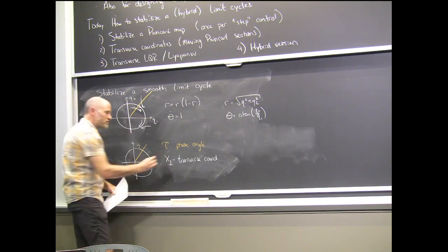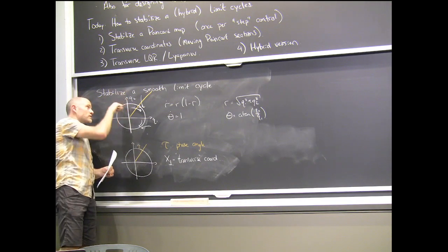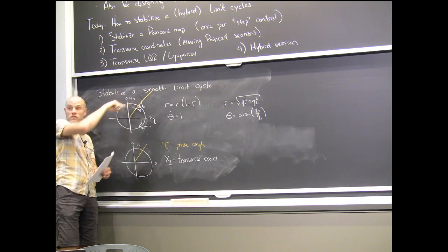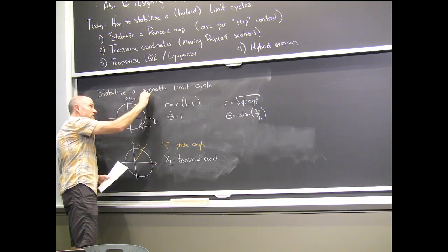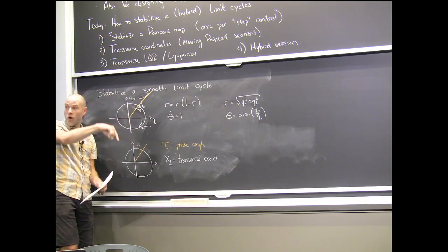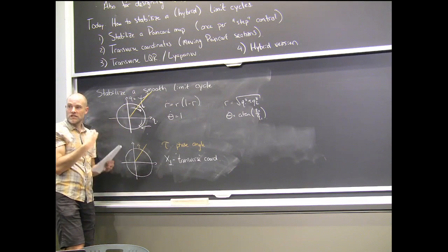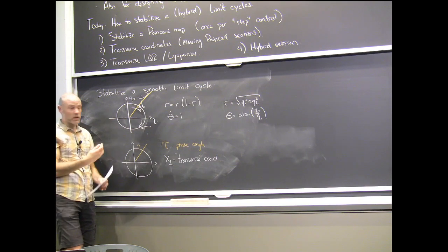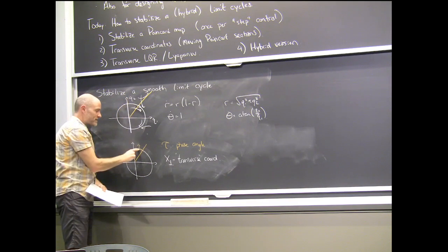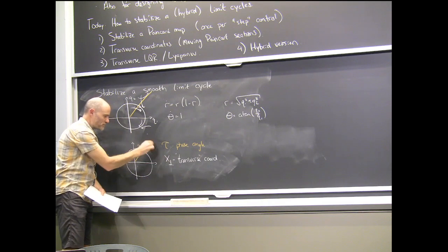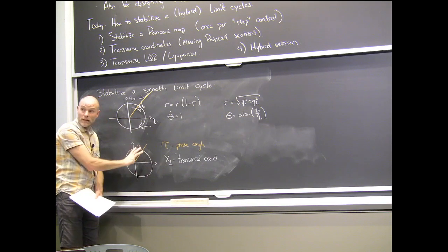Now the word transverse is important here. Just like the surface of section, what we wanted is that the flow was transverse, that all of the flow always went through the moving section, as opposed to any flows that could possibly take a glancing blow on that section. We want it to always penetrate the section. It doesn't have to be perpendicular to the orbit, but it just needs to be not parallel to the orbit. Then we can make this sort of moving coordinate system, where as a function of tau I have a different mapping from x to x perpendicular. But that's a function I could pre-compute around the nominal limit cycle.